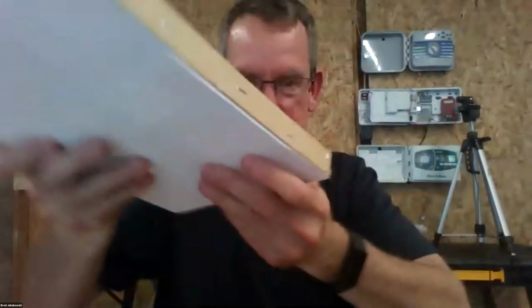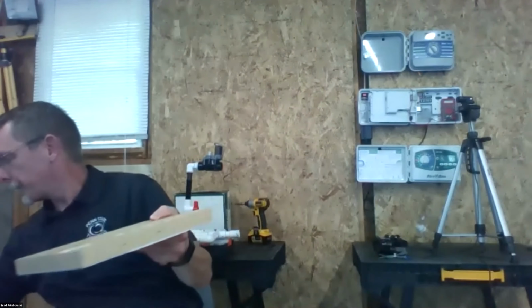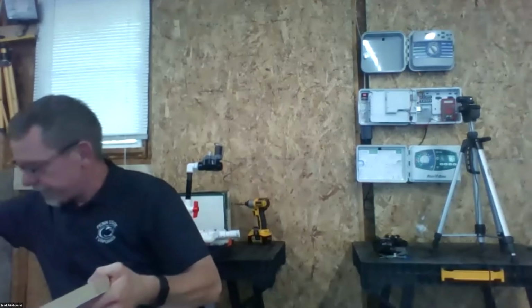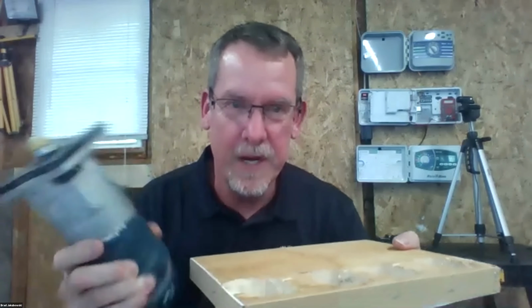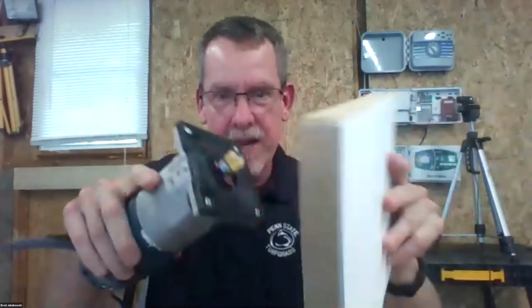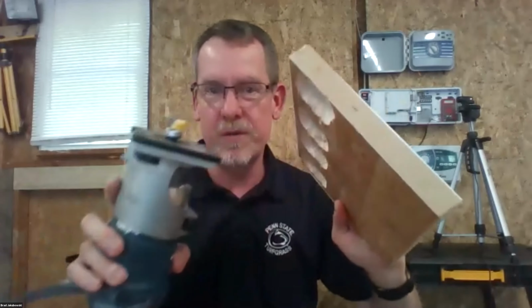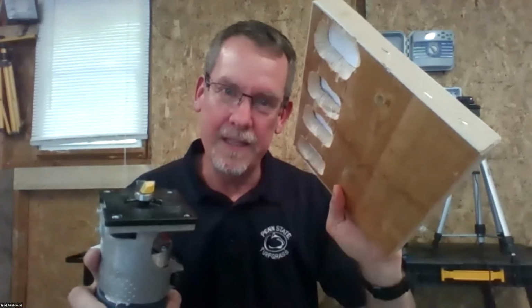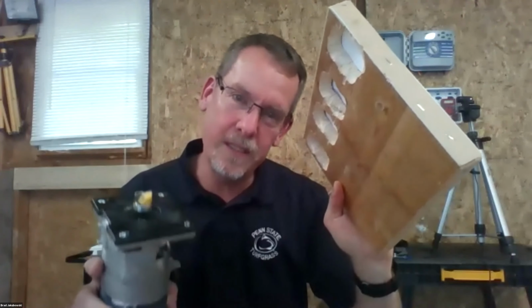You could place the piece of foam board, and it would stick out above it. So this way you could just lay this on the table and then get your router. If you wanted to go to this kind of effort, you wouldn't necessarily have to do this. But I got a 3/4 inch router bit like this with a bearing on it. This bearing would then ride around on the insides of that and trim out a little bit of the foam. This gave it a little bit of a recess to allow a flush fit between the two pieces of foam board.